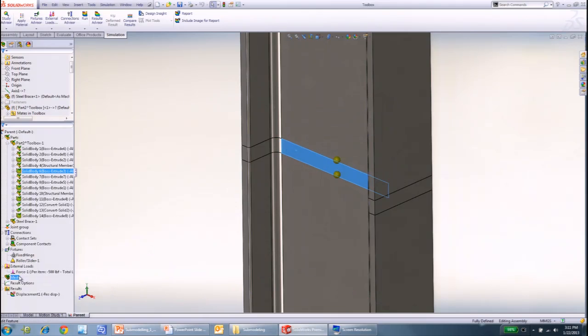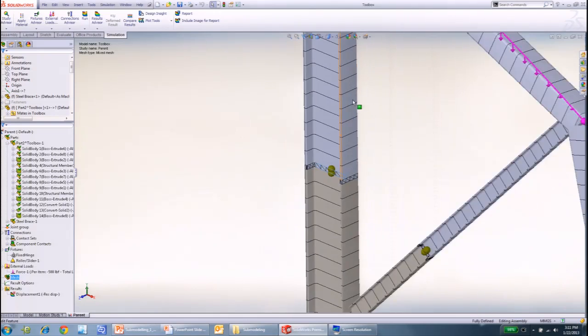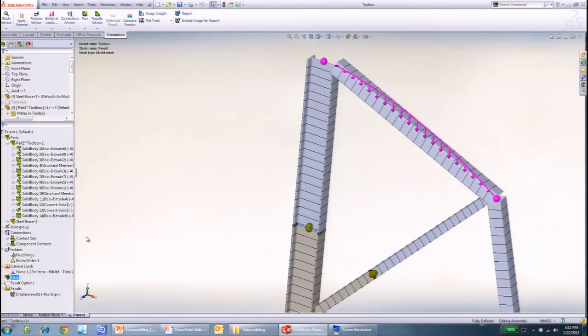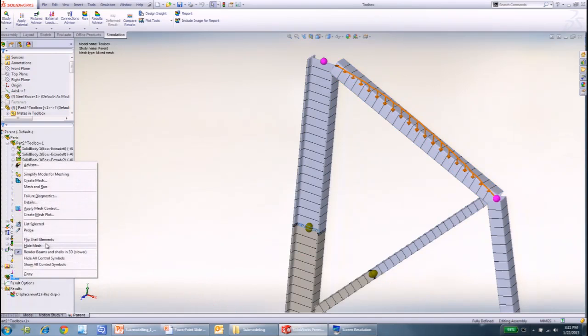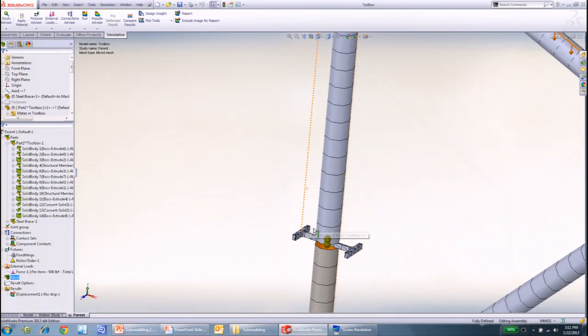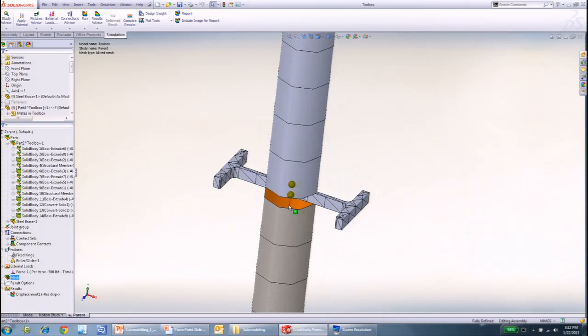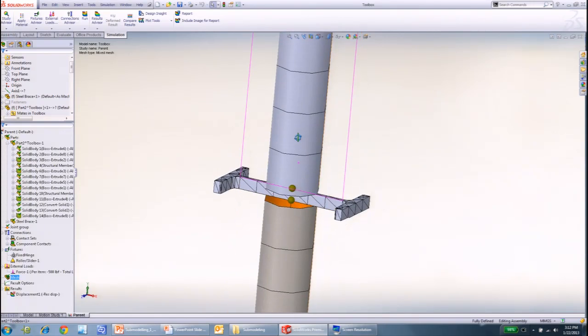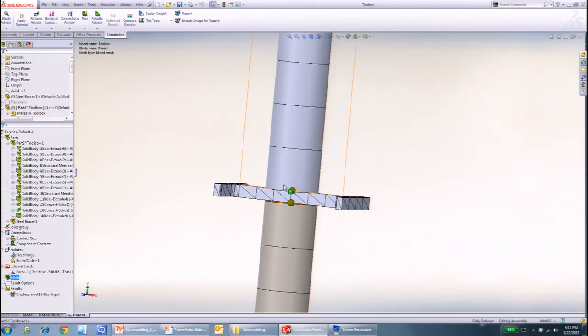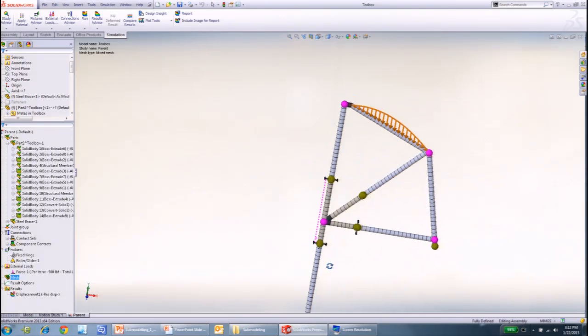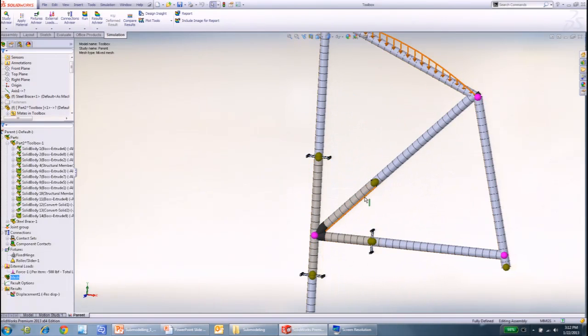So let me just show you the mesh. You'll see that this is a 3D representation of the beam. If you've not been using the 3D representation, it'll look like these cylinders, the 1D element. And then these are the solids I created just to transfer the load, because if these two are beams and gets merged, we cannot cut it for the submodel. So I've just introduced a solid element here, but inside this is all beams, because this closely represents the connection I have. I'm just going to include the details in the submodel.